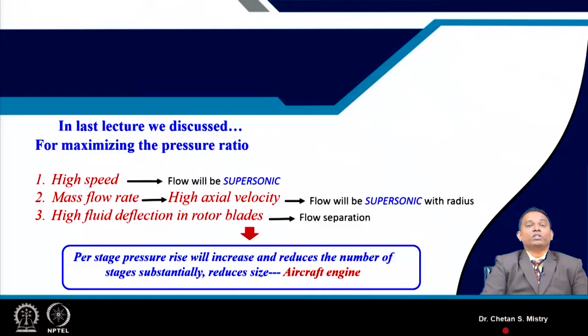Now, by any means, what we are looking for is a larger or higher per stage pressure rise in order to reduce the number of stages, to achieve compact, lightweight and fuel efficient engines for future aircraft. So we need to focus our study more towards developing a higher per stage pressure rise, and that is the reason we now need to address the issues related to supersonic flow.